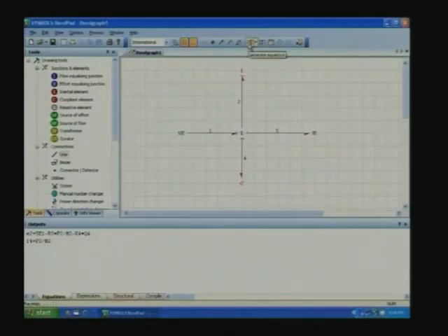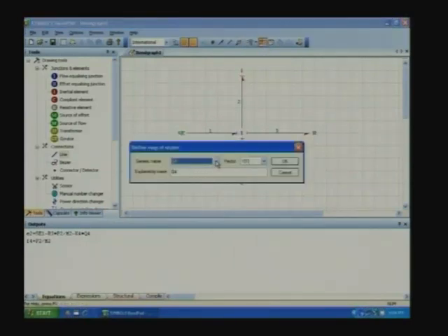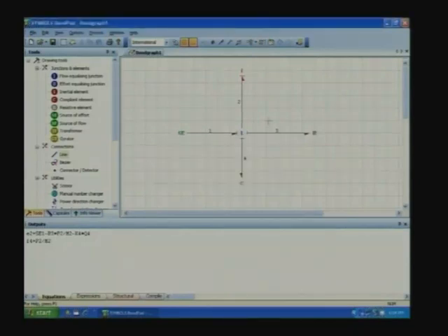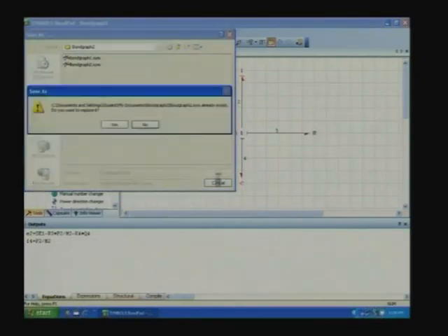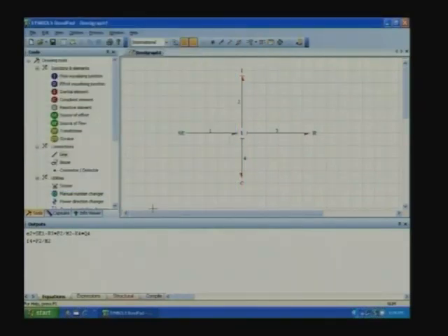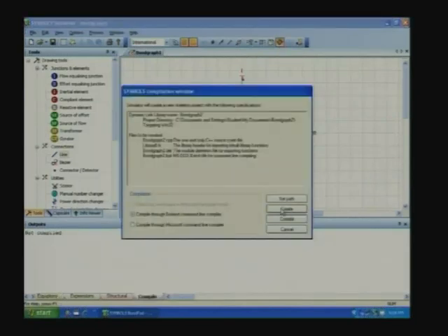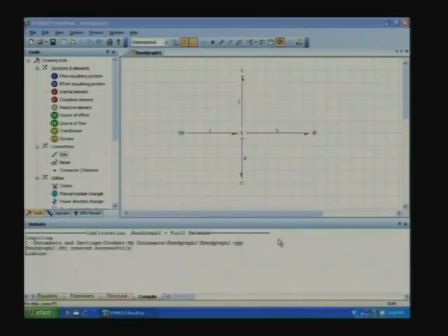Now, we have already generated the equations, now we have to define the maps. What are the state variables? Q4 and P2. We could give a name, but we understand what they are. So, let us leave that. Then it is to generate the simulation code. I will give it as bond graph 2 same, it overrides, fine. Now, we have to compile. So, set and compile, let us see what it writes.